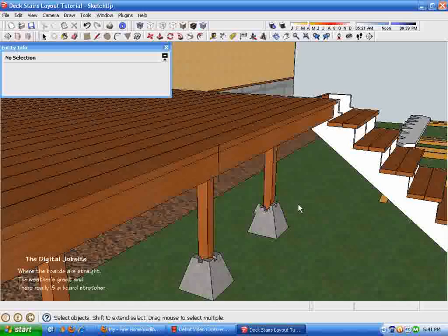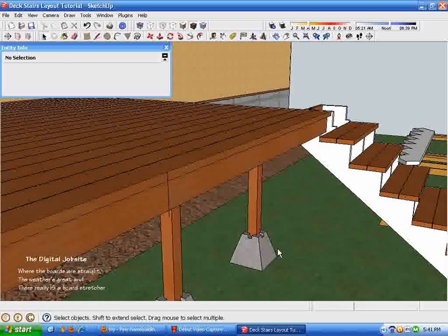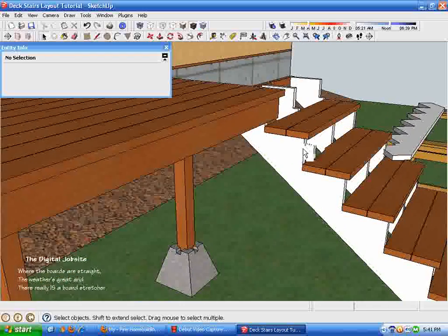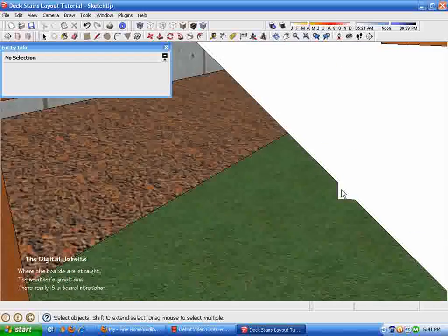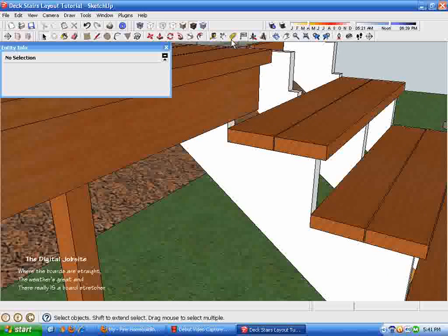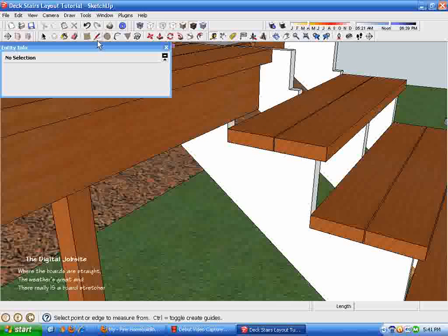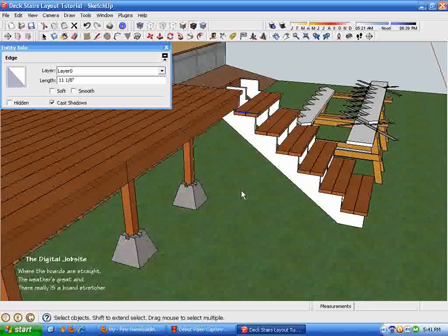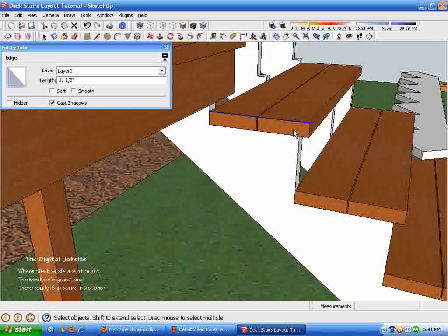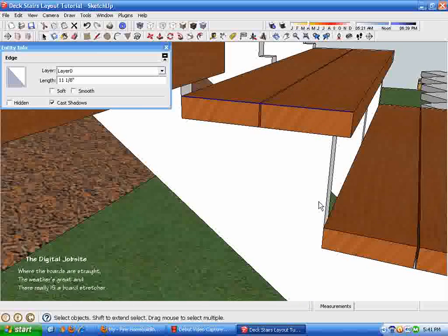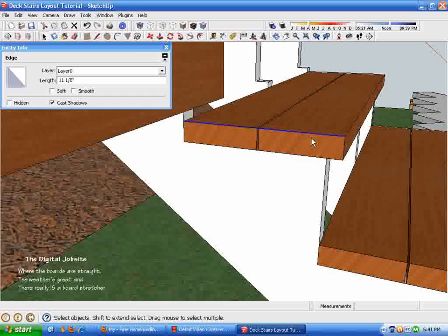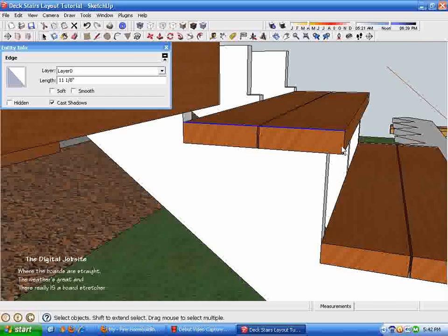For the purpose of the model, I'm showing a nominal redwood decking material, 1.5 inches thick and 5.5 inches wide, with a 1/8 inch gap in the middle, which gives us a length of 11 1/8 inches. Not too tough a math there. And the tread width, in the stairs that I build, I'll make the individual run 1 inch less than the tread width to provide a 1 inch nosing. It just makes the stairs more comfortable to go up and down.